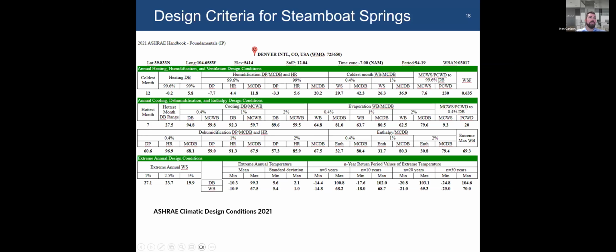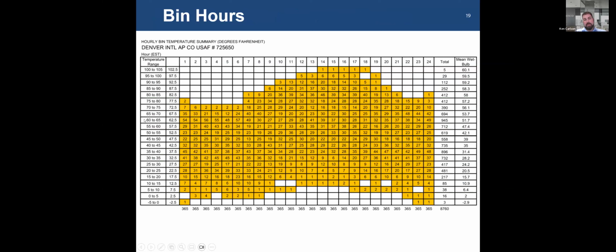So where did they get this information from? I'm going to show you in this next slide. This is something that we often use to evaluate HVAC systems, to calculate savings and costs, and to do load analysis. This is data, right? These are hours, for Denver International Airport. These are the temperatures, and these are the number of hours at each hour interval within that temperature. In January there were 7 hours, and I should note this is averaged over multiple years. They haven't updated this in a while, but it averages from about 1993 to 2005 or 2007.